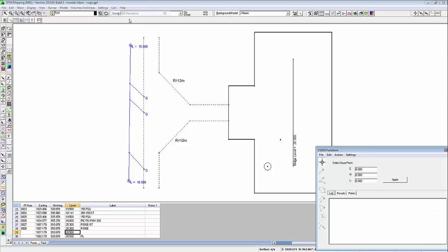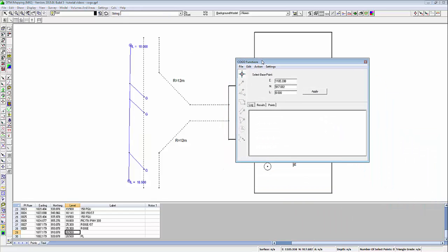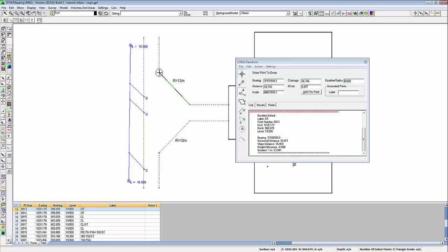So I'm going to use Calc Cogo now to add in a radius around this channel line of a road. You see we've given points for the tangent points, and the text tells us it's a 12 metre radius. So we create a baseline from the tangent points, and now we can enter a radius along this baseline, it's 12 metres. So the red line shows us our baseline with a radius attached to it.